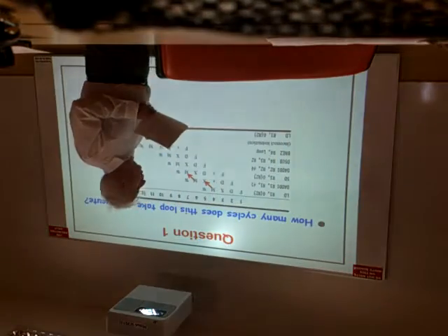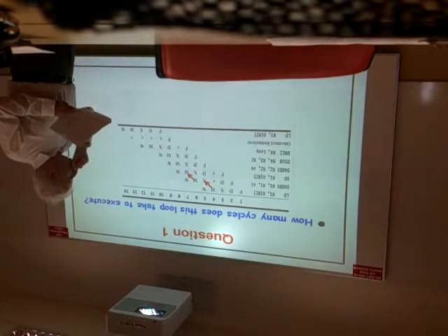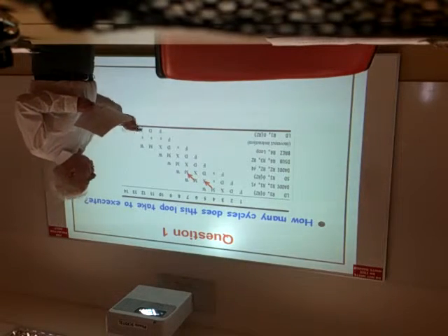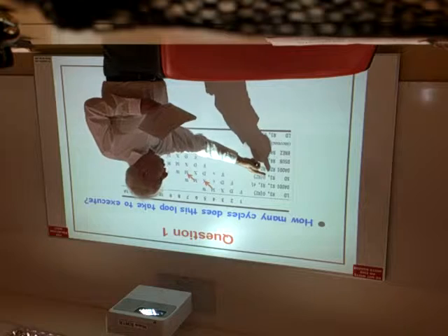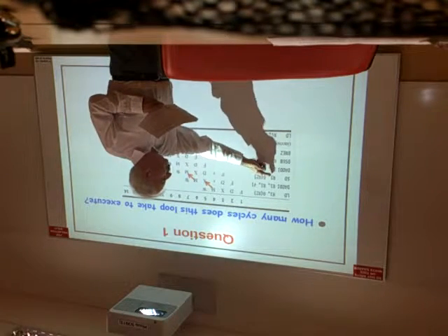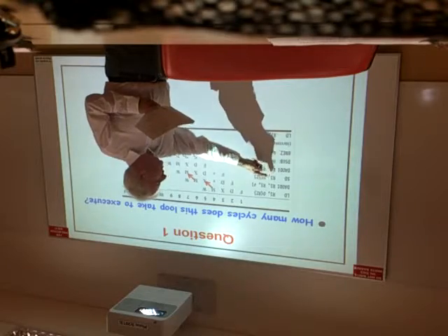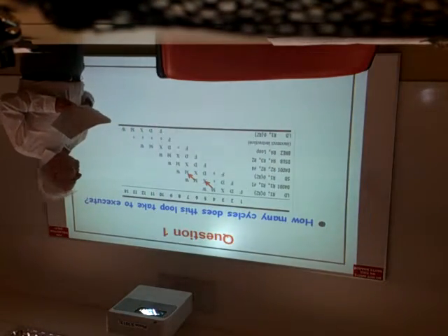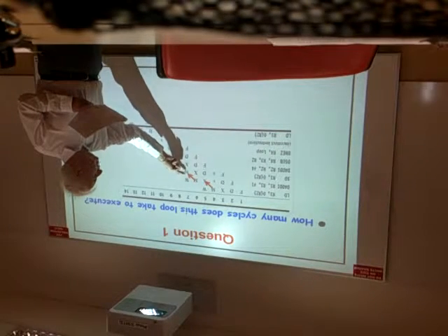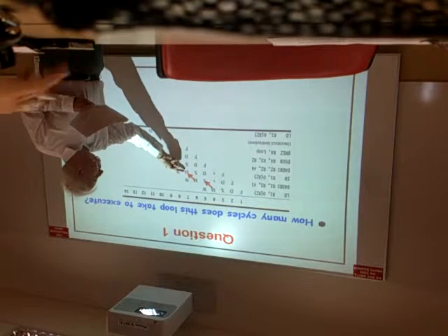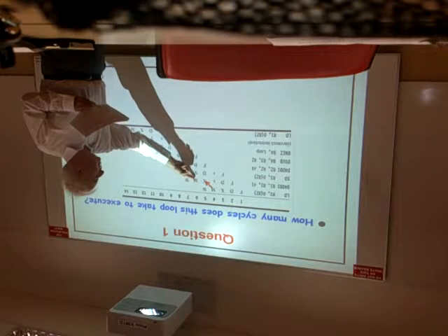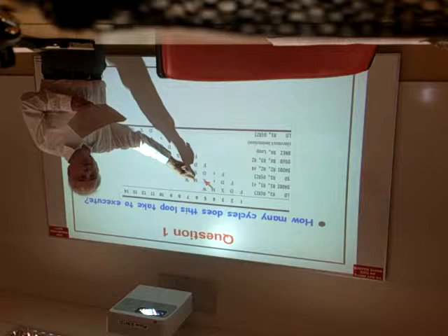This one can forward during the memory stage. In this full forwarding case, we don't need to store the value into memory until we execute the M cycle. So we need the value of R1 in the M stage of this pipeline, so we can forward it in the previous stage.